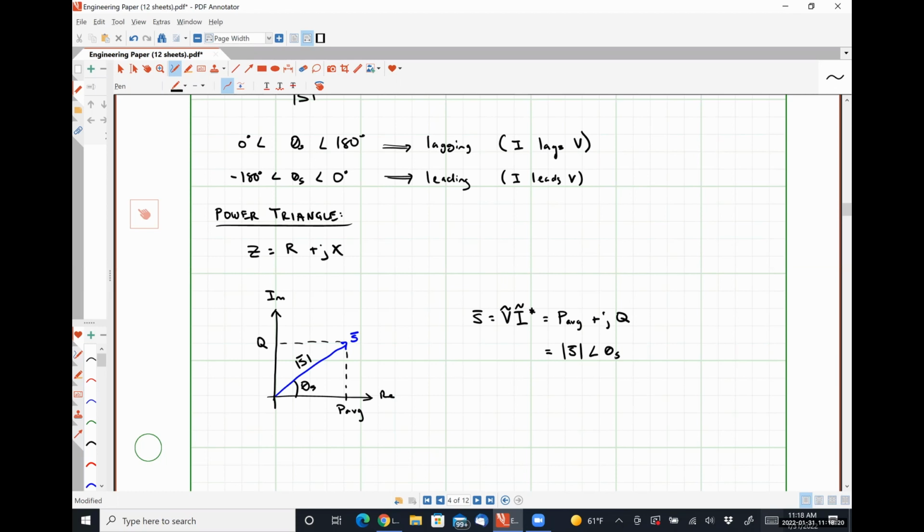They know the RMS voltage, and they know the current. And from that, they can tell for an individual consumer based on their monitoring system what your power factor is at any given minute. And if it stays low for too long, such that on average, your power factor was below the threshold for that billing cycle, you would receive a fine.